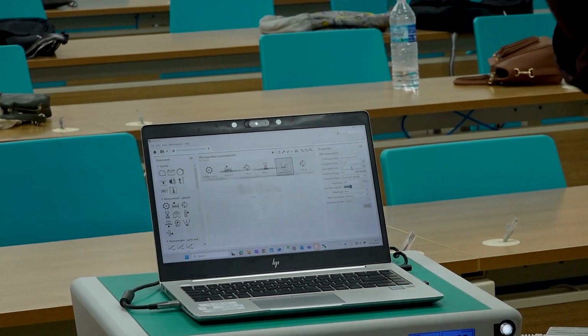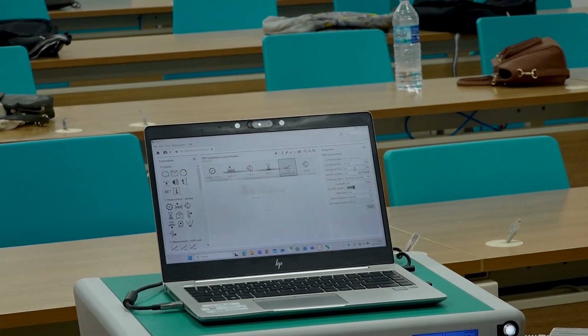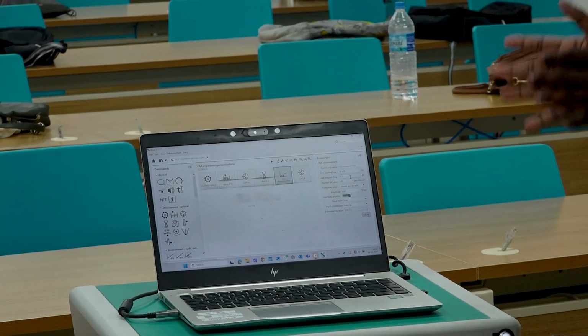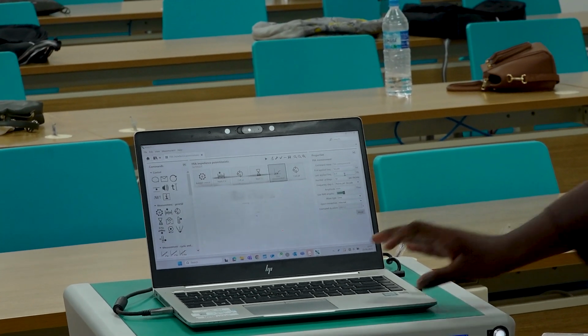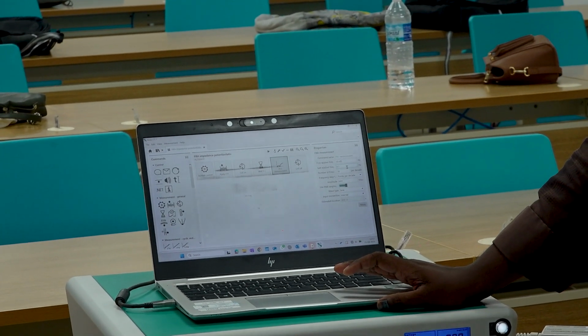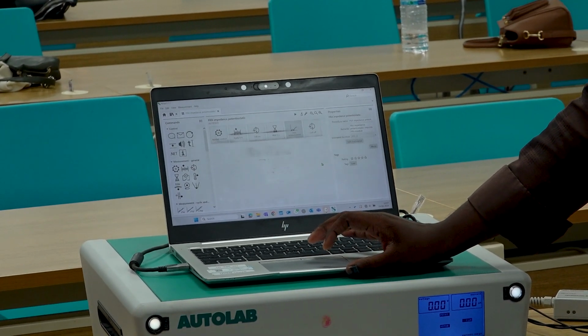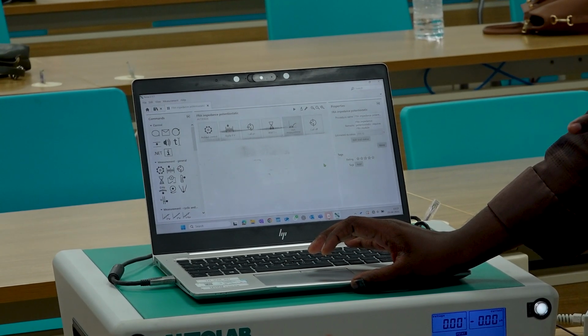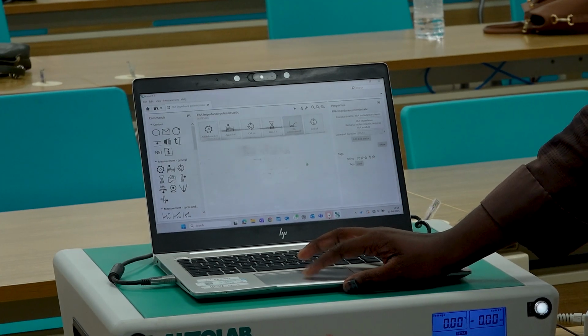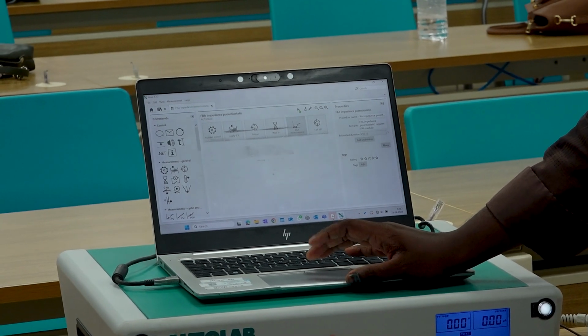You have to remember these decimal forms, because most instruments take only decimal forms. Okay, so we are going to sweep from 100 kilohertz to 0.1 hertz. That's it. Is this sine wave or frequency? Frequency. Okay, so let's start.